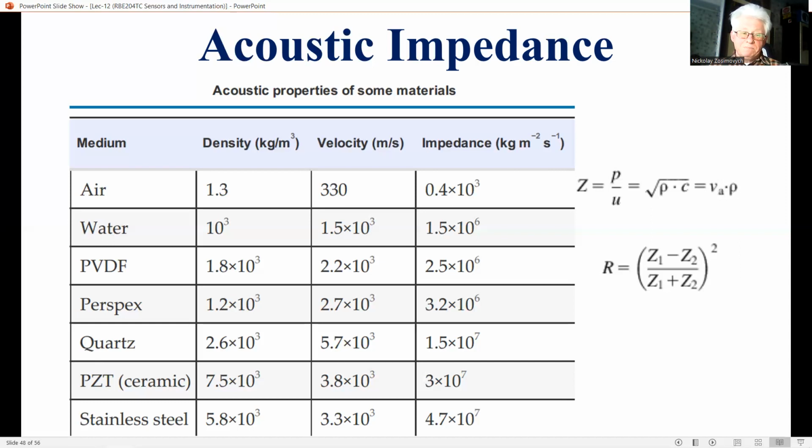This has two important consequences for the S over N in TOF measurements, where emitter and receiver are both facing the reflecting surface. First, an airborne sound wave that arrives at a solid object reflects in the same way as light on a mirror. Waves with an oblique angle of incidence reflect away from the direction of the emitter. So the reflected sound only partially arrives at the receiver, which is usually placed very near the emitter.